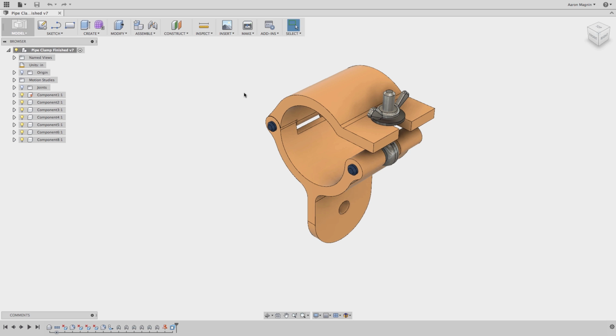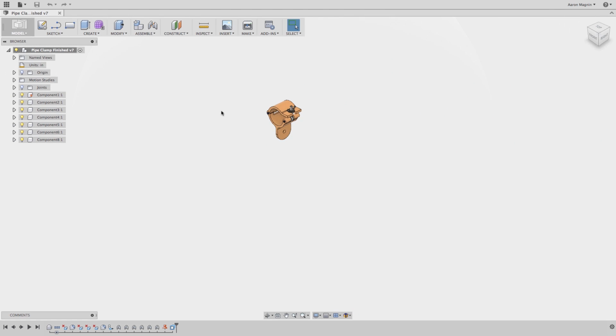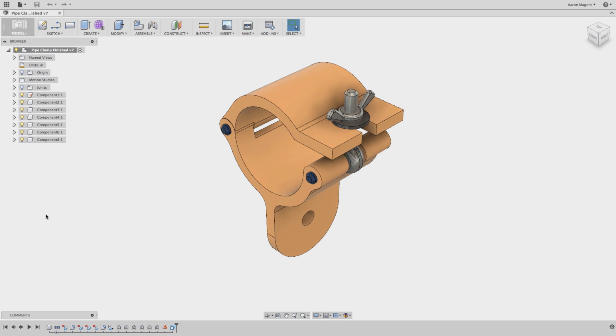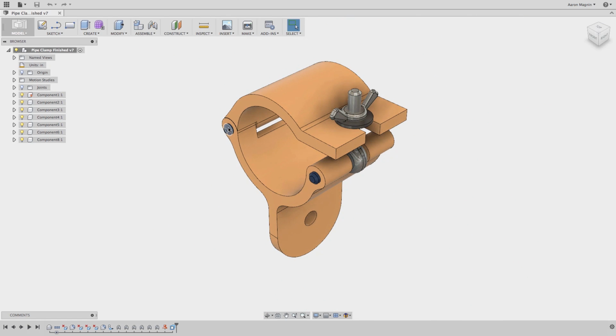If I instead want to zoom in and out, I can spin the wheel one way or the other, and you can change what one does or the other does. One thing to pay attention to is that wherever your mouse is pointed, that's where it wants to zoom into. So if I'm down here in this lower left-hand corner, I'm going to lose my model. So that brings up another nice little shortcut. If you double click the wheel, it actually does a zoom to fit. So you're looking directly at this model at a scale that is appropriate for what we're working with. So let's get my mouse cursor back in here and say I want to zoom really close on this guy. Just pay attention to where that mouse is pointing and spin that wheel.